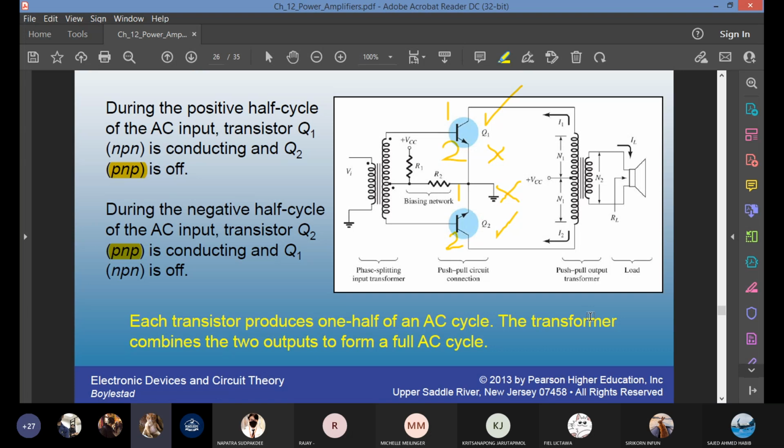The highlighted one we have to change, right, Ajahn? Yes, the highlighted one, please change it. Change to NPN. From the symbol, it's obvious, it's NPN. If it was PNP, the arrow would go inside the body of the transistor, but it does not.